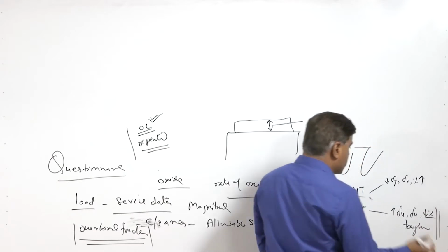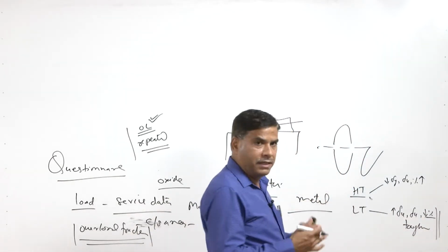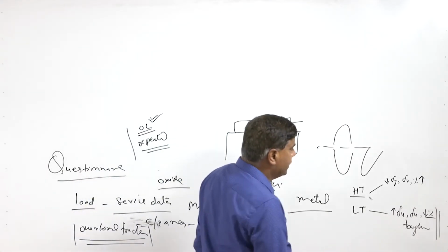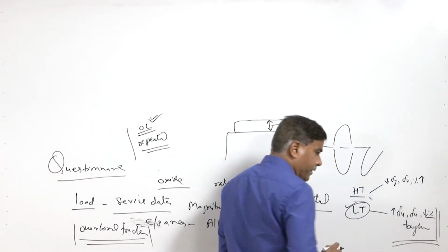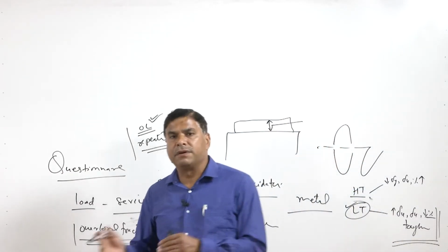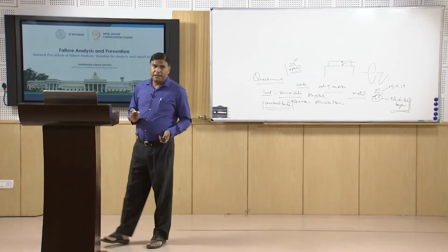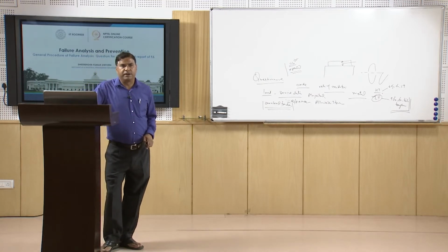So, those components especially which are sensitive to the temperature, and if they are subjected to the transition from ductile to brittle behavior, then it is very important to mention the temperature at the time of failure. So, we need to identify basically whether the temperature at the time of failure has been specified or identified or not.